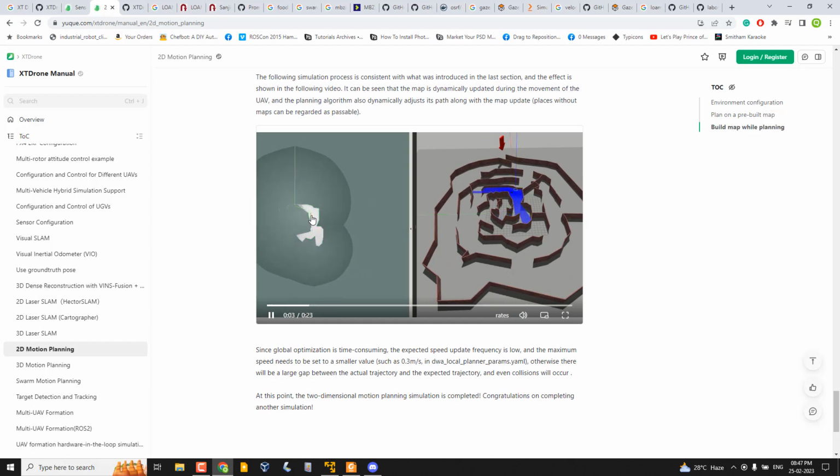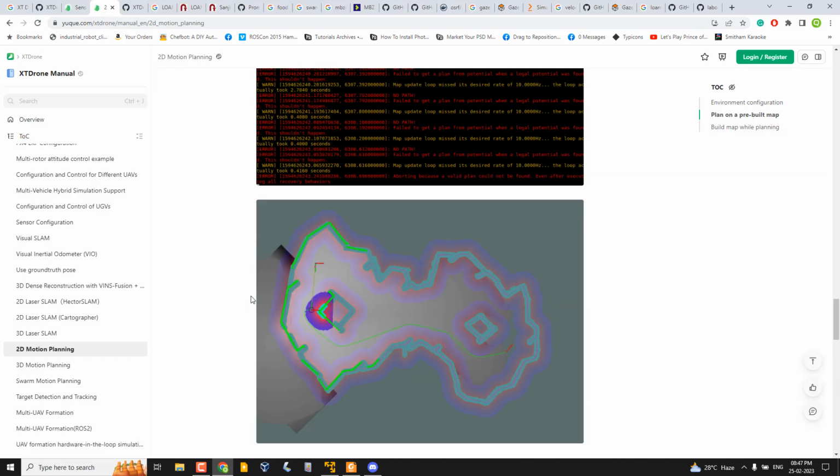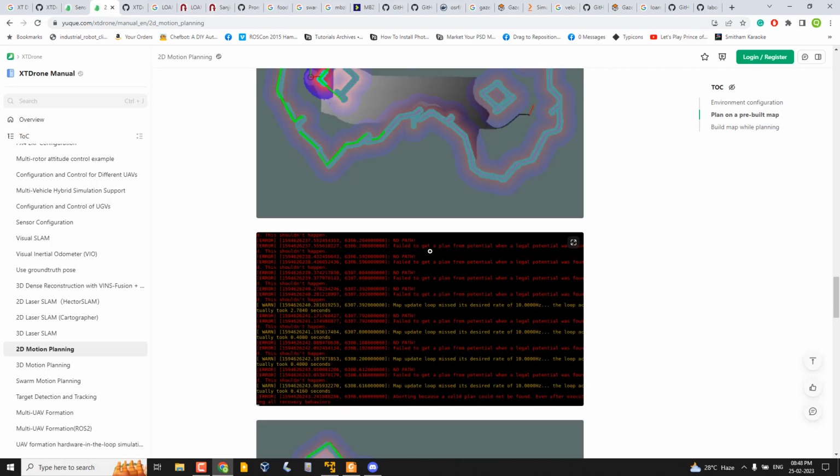Here you can see the Hector SLAM is running, and it is running a kind of exploratory algorithm. The map is being built, and the robot is exploring in this maze. So this is also a good example. If you want to set up 2D based navigation and mapping, I think this will be good. You only need a laser scanner on the mobile robot.